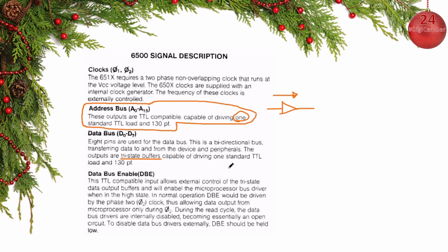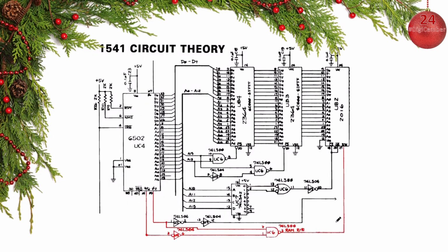And I do also have some concern about the Phi2 clock and the read and write cycle to memory, because I've looked at some schematics now and they do some trickery there. And they also have the data bus enable signal that should be held low if you don't use it, and that we have not taken into consideration. So there are some concerns with this, and if we actually look into some designs, this 1541 is a very